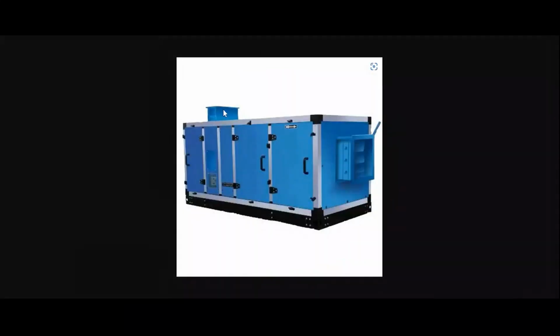So you are able to see how the AHU looks with outer panels. These are all access doors. This is the supply duct mouthpiece, and this is for return ducting. You can ask me, how did you tell me this is the supply duct and this is the return duct? You can see the arrow mark right here. This arrow mark indicates how the air is flowing forward. Okay. Next.